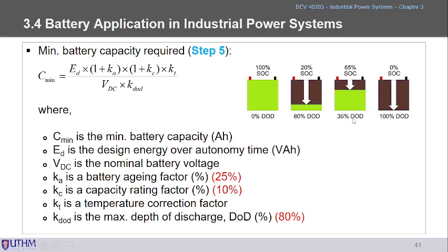In this case, if our battery level is 65, then it will auto charge again here. Of course, this is not recommended, as this one also is normally not recommended, especially for lead acid. For lead acid we normally take 50% only for this type of battery. Okay.